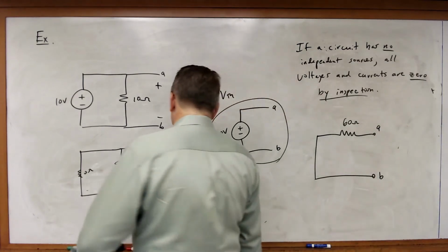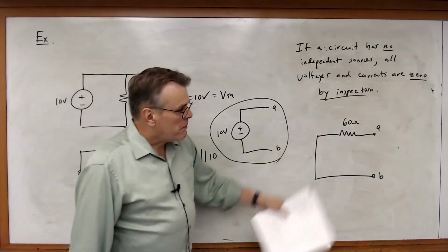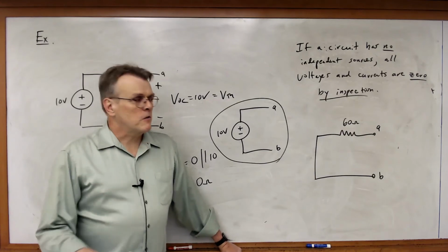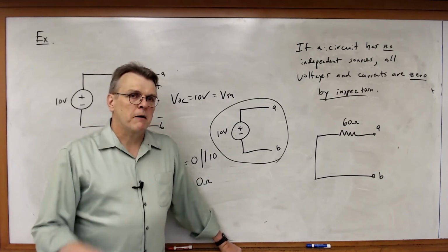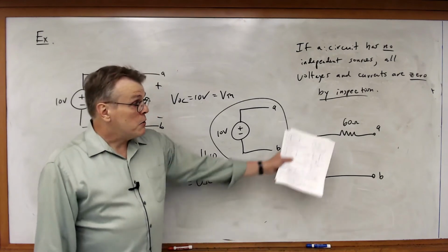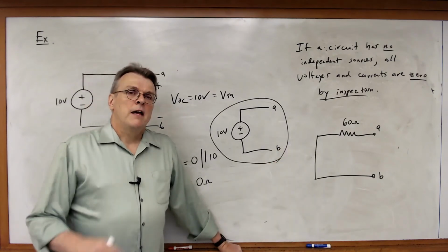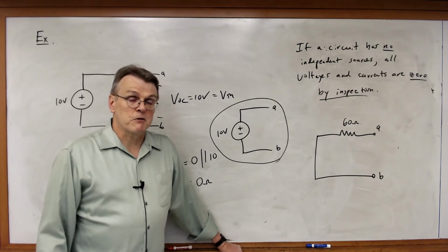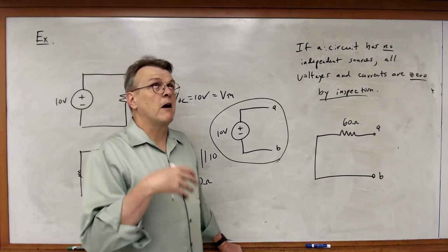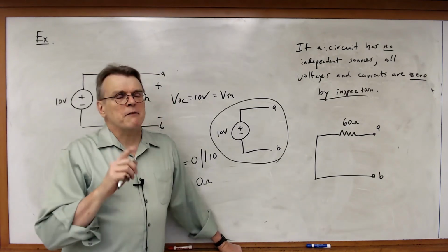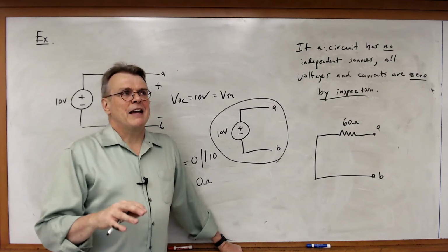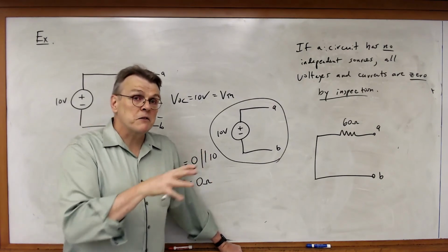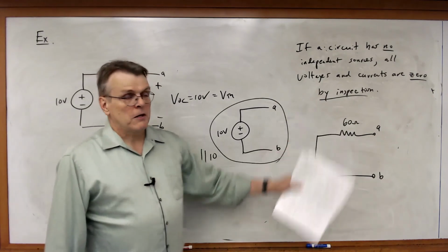Now there's another question students will often ask. Is it possible for a Thevenin resistance to be negative? Yes, it is. With certain types of feedback configurations, depending on how the circuit is constructed, you can have a negative resistance. If you take a more advanced course in electronics, you will learn that the indication of a negative resistance is a phenomenon called positive feedback, which results in oscillation of the circuit, building something called an oscillator. That's really beyond the scope of a Circuits 1 course, but it's certainly possible.